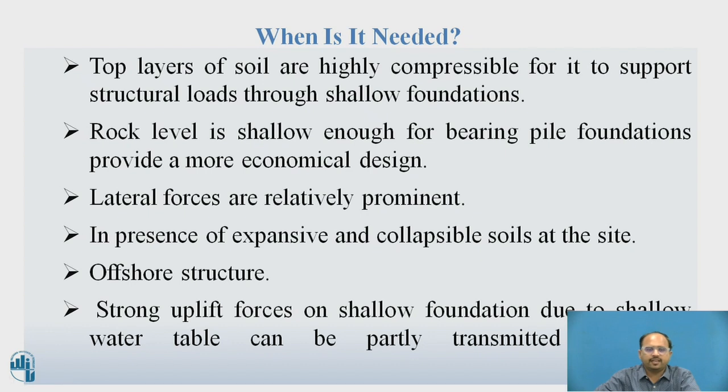When is a pile foundation needed? If the top layers of soil are highly compressible, the structure load cannot be carried by the shallow foundation. If the rock level is shallow enough for bearing, a pile foundation is a more economical design. If the hard strata is at a very deep depth, in that condition we can use the pile foundation, and it will also give an economical design.